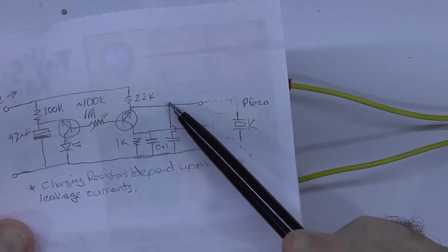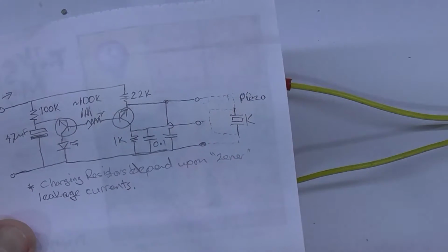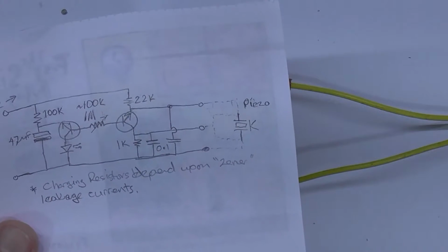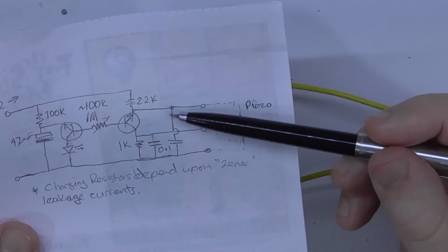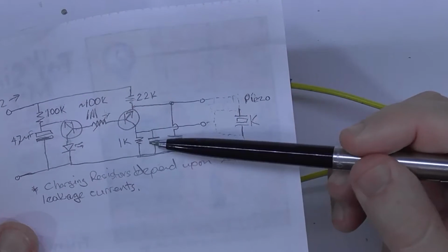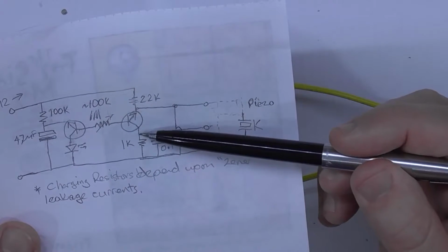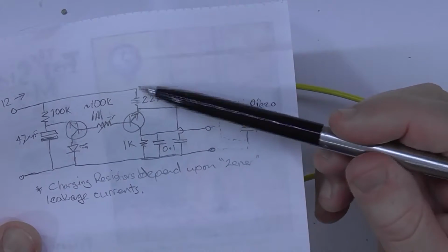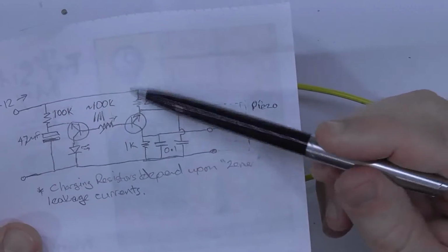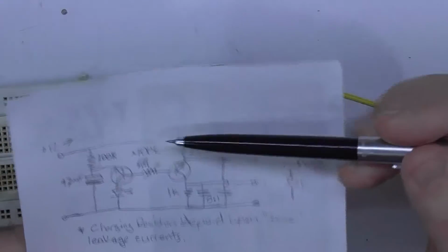So it then begins to charge up again, and consequently goes through the process. Now obviously, if I did not have that 1K resistor there, I would expect it to continue to dump charge into that 0.1 microfarad capacitor until it can no longer, between the supply voltage and the voltage that's achieved at this point, get enough threshold to switch on.